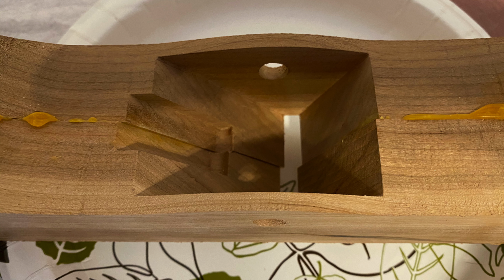Somewhere along the line of carving the two pieces, the X position had shifted about 1/8 of an inch between them. You can see that offset looking into the throat of the two halves of the hand plane prototype. Turned out that a set screw on my X-axis had loosened up, which was a quick 15-minute fix, thankfully.